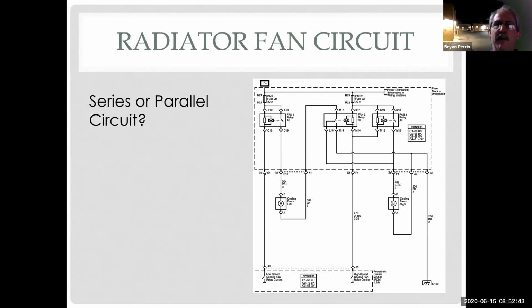So you can see where I might have a car that overheats or the high speed fan comes on a lot. The customer might complain about the noise because one of the fans is broken or one of the wires is broken. So now only one fan works, which means you have no low speed.